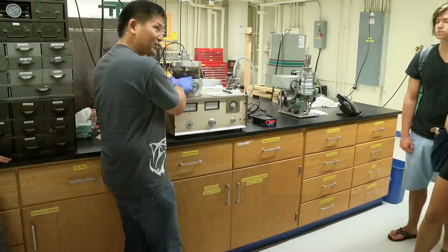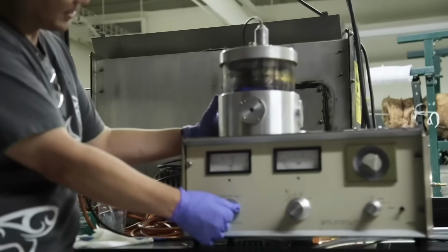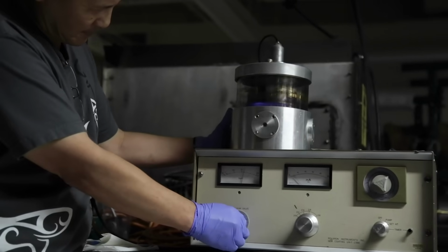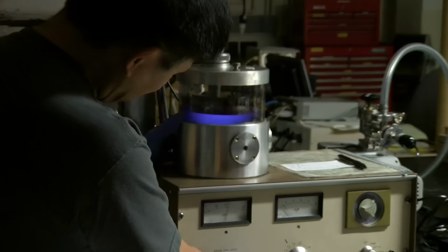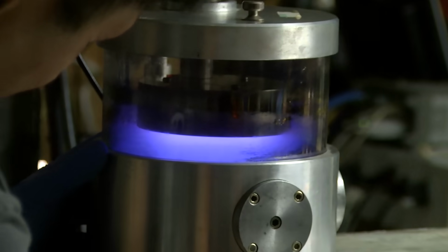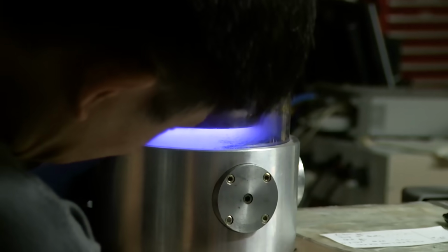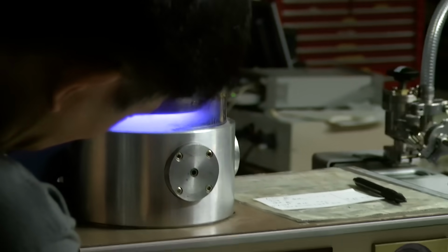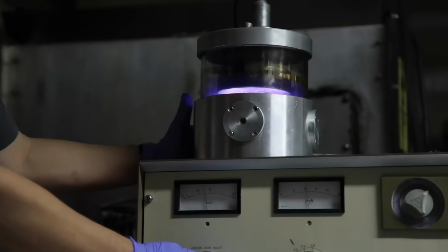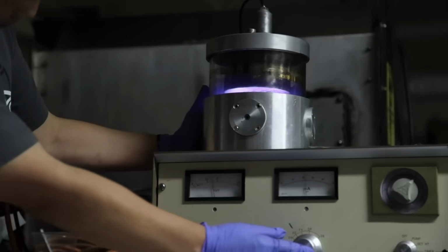If you look through this glass jar, it's going to be a little bit of a glow. Some of you might be able to see it already. Come a little closer. From where I am, you start to see the glowing purple plasma. That's the ionization of the argon, causing it to electrostatically accelerate towards the gold target. That's blasting off gold atoms that are then coating the stuff that Reed's coating, that you'll see in a sec. But this is a controlled application of ionization and radiation damage using a couple of kilovolt argon ions. I don't know if you call it a beam, but at least an argon ion plasma.